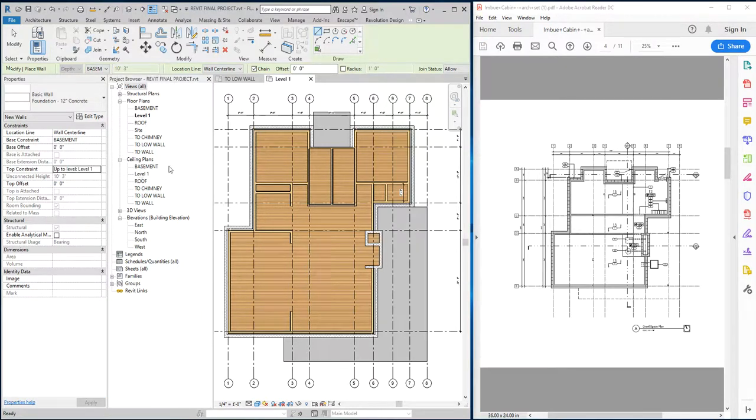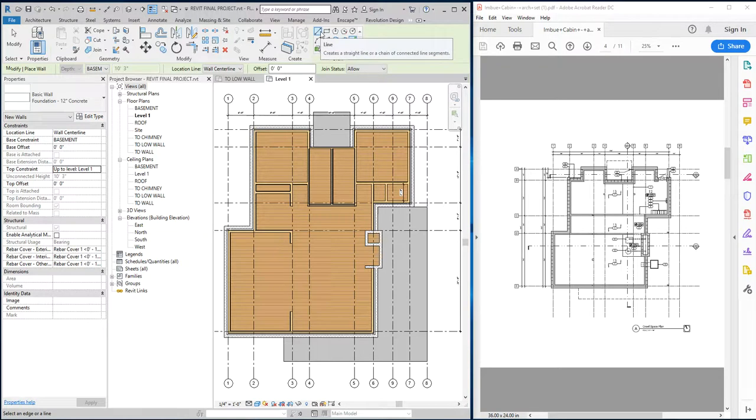All right. And so now I'm going to use my little picker tool here, which is pretty handy. I also could have used my line tool here, and I'm just going to start picking walls, essentially. I'm going to choose to define my walls from the finish face exterior. So as I pick around the edge of my project here, right, if I pick on that outer face, ideally, the walls should form from that outer edge and grow inside of the house.